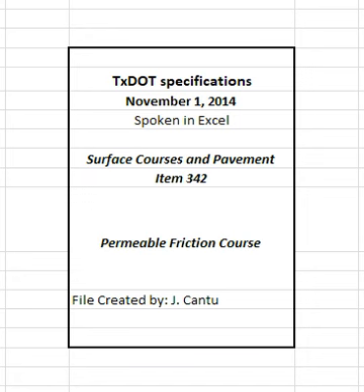4.4.2 Job Mix Formula Approval. The job mix formula, JMF, is the combined aggregate gradation, design level, and target asphalt percentage used to establish target values for hot mix production. JMF1 is the original laboratory mixture design used to produce the trial batch. When WMA is used, JMF1 may be designed and submitted to the engineer without including the WMA additive.